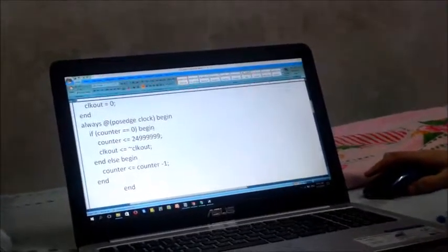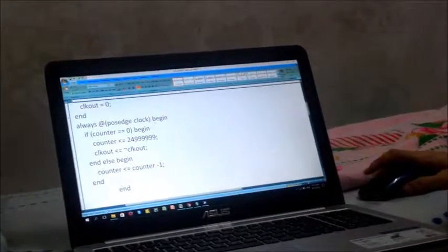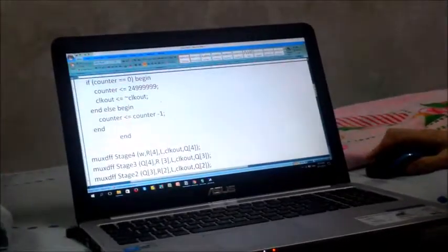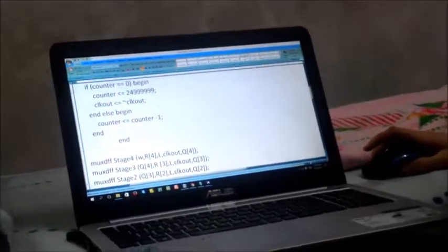And then, when we set them equal to 0, we have written another piece of code which is an always block that involves both of the variables. And this always block will be in charge of controlling the clock signal in order to make those LEDs blink. And that's all from me, and I will pass the rest to Nazmi.